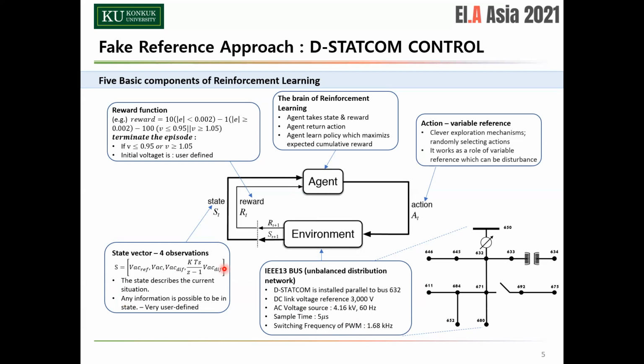And I feel you might be familiar with these forms because they are just PI terms. So the idea about the composition of our state component originates from the input of a PI controller, which creates a proportional and integral term from the error generated by the difference between the measurement and the reference, like here. So you can see the difference like that.